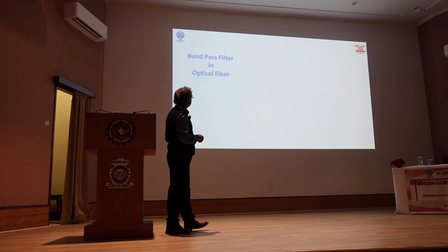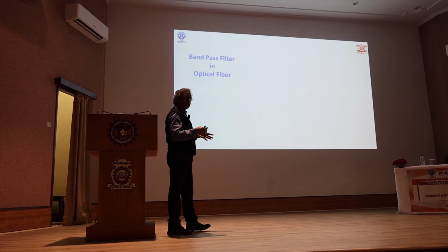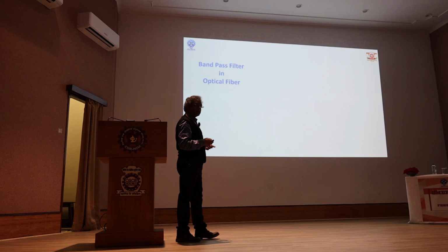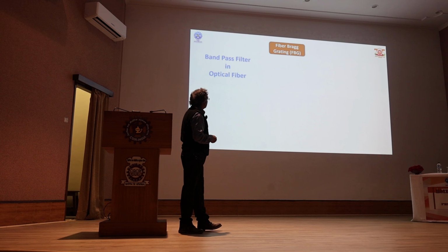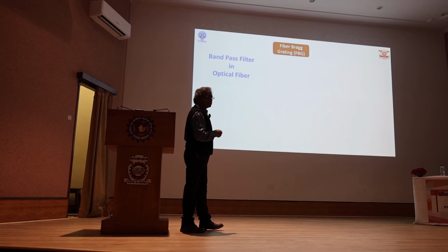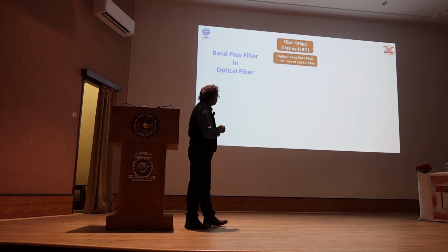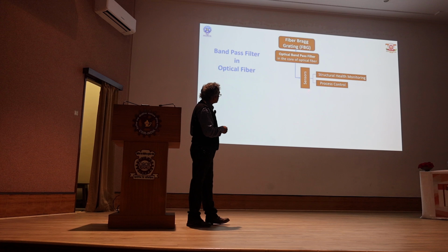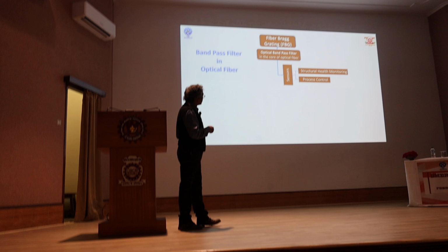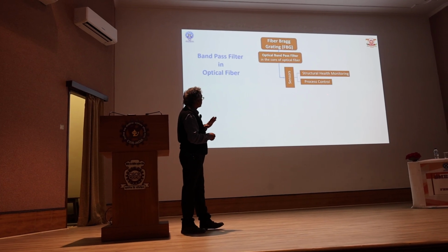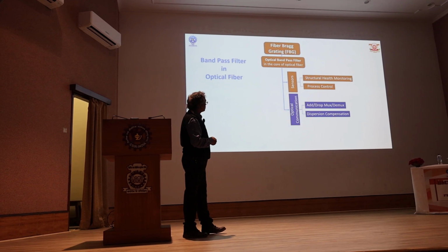Now, let us switch over to the bandpass filter in optical fiber. So what we are doing, instead of using a bulk glass, we will consider an optical fiber and we will try to devise this particular bandpass filter in an optical fiber. So, I will now coin this term, optical fiber Bragg grating. What is this? It is nothing but an optical bandpass filter. First, to give a briefing about its merit, we will see that this optical bandpass filter, when it is inscribed in an optical fiber, can be used as a sensor for structural monitoring and process control monitoring.